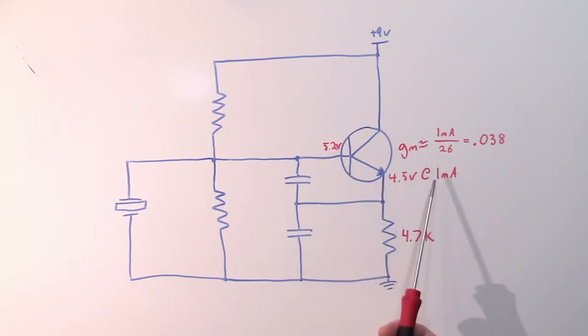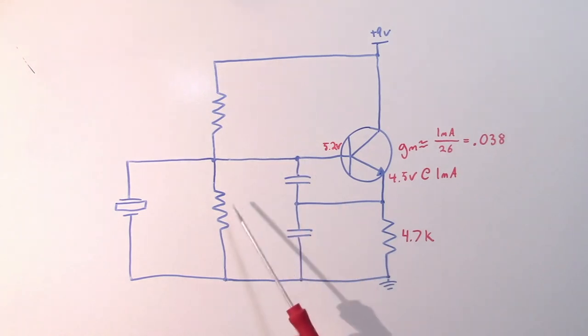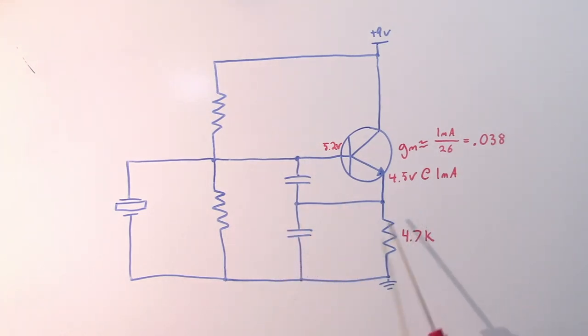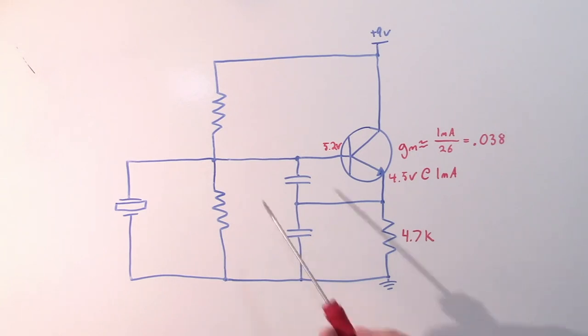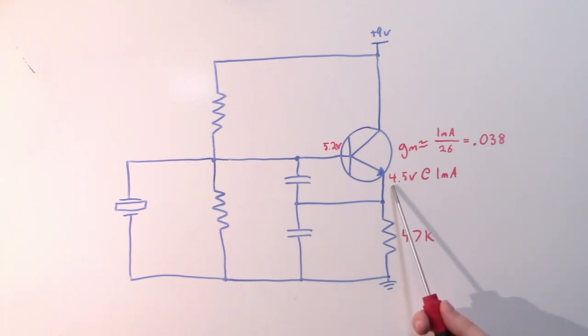that they're negligible. So a good rule of thumb is to select these resistors such that their parallel combination is not more than 10 times your emitter resistor. So selecting a larger emitter resistor means we can select larger base resistors, which means we have a larger input impedance, which means we have a better loaded Q. So this is another advantage of setting a larger quiescent emitter voltage.